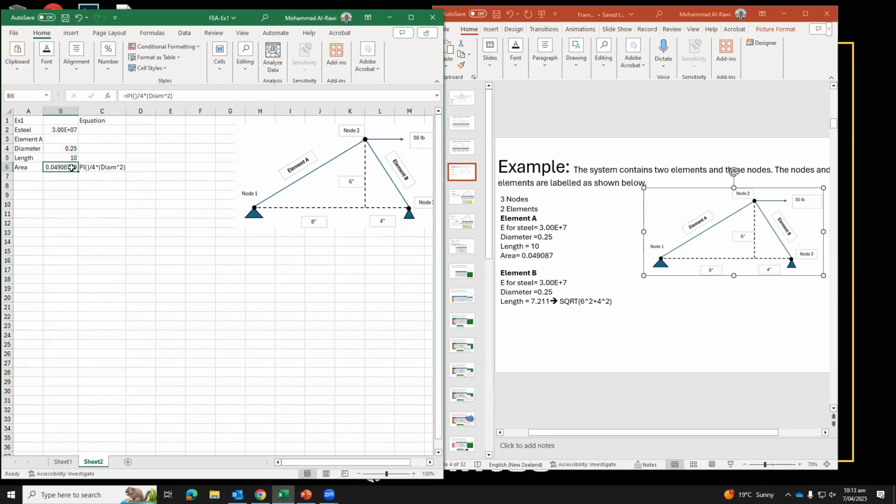So that as well, instead of B6, I could call it the area for that beam, okay? So that is the area. So I'll call it here area. And then when I need to calculate with that, I just type area, and this Excel file understands to call that cell called area. So here is naming the area. Here is where you can generate the function.